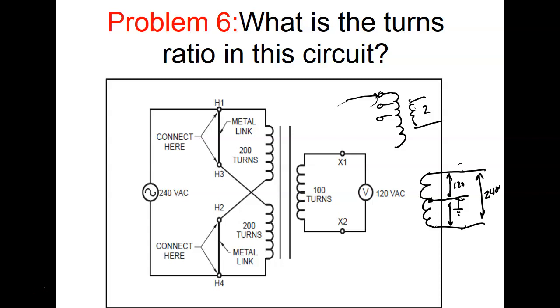First of all, another reason we hook it up to ground is that if a hot lead shorts against the metal, it's going to pop your breaker or blow your fuse. If you don't do that, then that metal can also carry a true charge, not an induced charge, but whatever that thing's rated at. So don't always run your grounds.